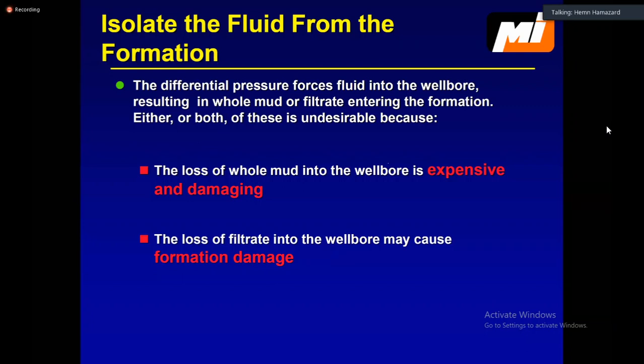You have a formation pressure, just for example, of 1,500 PSI. This is your formation pressure. And then if you multiply by that calculation I showed you guys, your mud weight by vertical depth by the conversion factor, for example, you end up with 4,000 PSI. 4,000 PSI is way, way greater than 1,500. So in that case, 4,000 minus 1,500, so 2,500 PSI can push your pipe so hard to the side of the hole, to the slick equipment, slick tools. That means the tool is one size from top to the bottom. That means slick tools can adhere to the side of the hole. So instead of your pipe staying in the center of the hole, it goes to one side and adheres there, it sticks there, and you need millions of pounds to make it free.